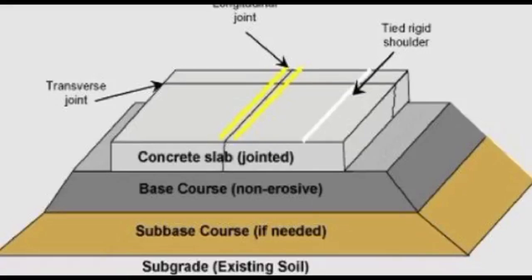Rigid pavements: stresses at slab edges promote cracking in rigid concrete slabs, ranging from narrow hairline cracks during drying to wide cracks of 0.15 centimeter, causing water entry and partial loss of aggregate interlock.